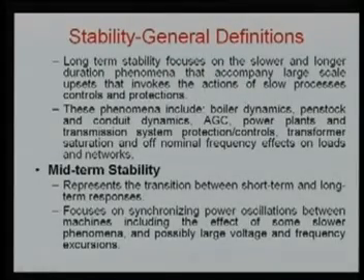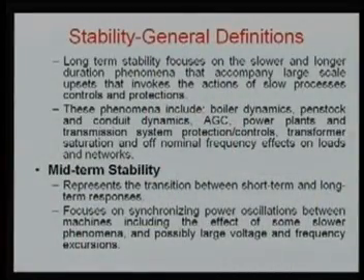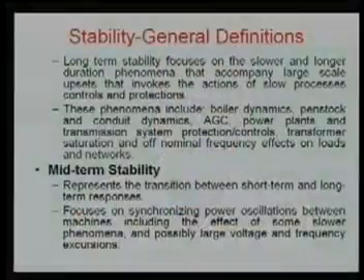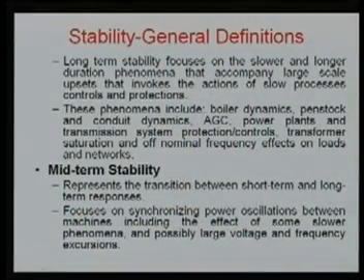your boiler dynamics. You know the boiler dynamics, all these mechanical devices, you must be very careful. All the mechanical devices including your governors, boilers, penstocks, conduit dynamics, they basically have a high, large time constant compared to your electrical system. So, if you are going to include them and they are going to impact the stability of the system, then it is called your long term stability phenomena, and then you have to take into account the various dynamics like boiler dynamics, governor dynamics, etc., along with your AGC, power plant, transmission system protection and controls, transformer saturation, off-nominal frequency effects on the loads and the networks. All of these, if included, fall under long term stability phenomena.